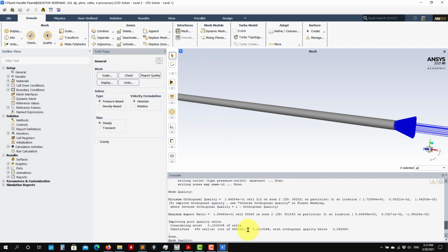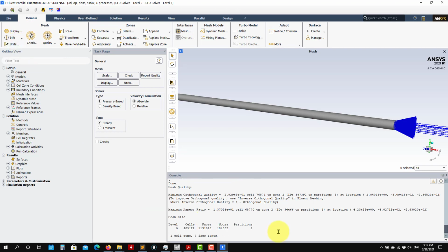So these are options that I show you now here in 3D where they are useful. In 2D, most of the time you're going to get good quality meshes, small meshes, and good scaling, so there is no need to check that one, but it's one you can check. And also here you go in info, size. See here that you have the mesh size, memory size, a few options. So now let's set up the case. We have done everything, so let's follow the vertical workflow here.